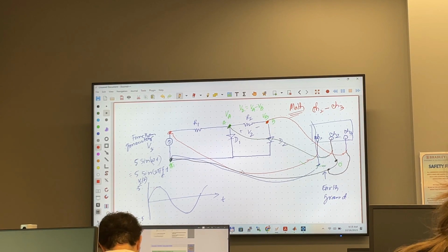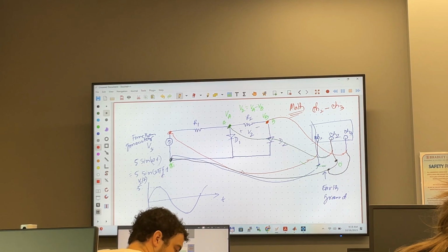There are some other circuit simulators as well in MATLAB Simulink. I teach this in mechatronics. It's called SimScape. Using SimScape, you can draw exactly the same circuit. Only thing is that in SimScape, you need to add another solver.